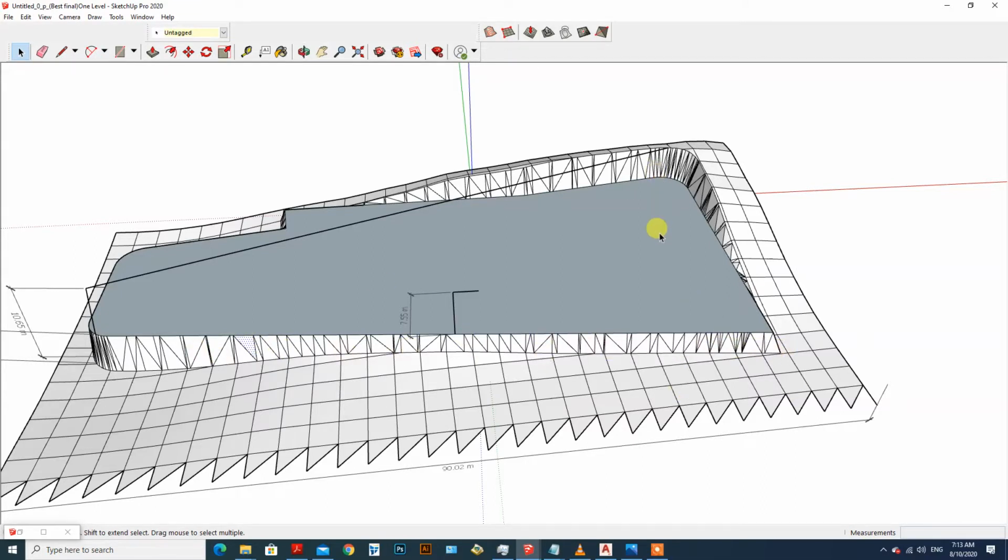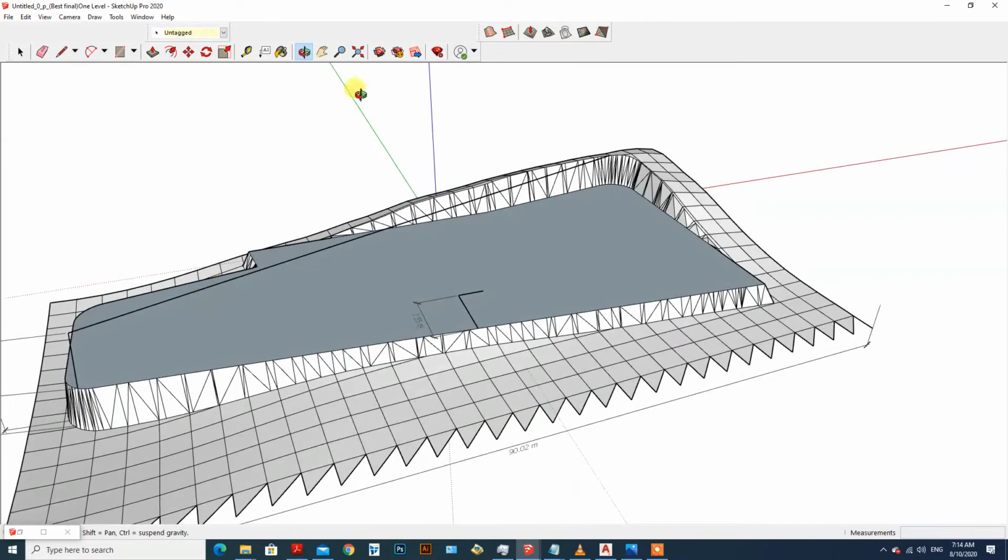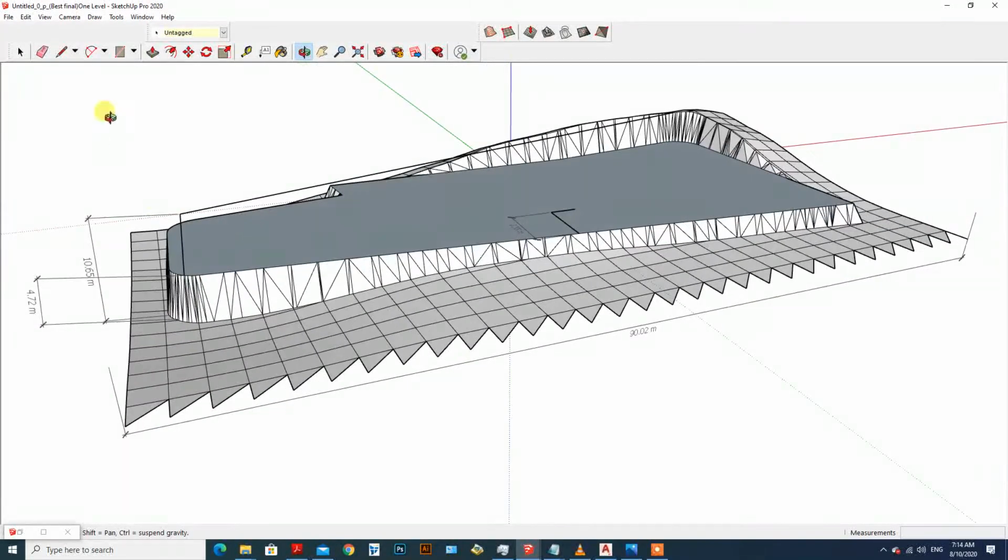It's going to be a slope. We do our cut, and this is going to be the fill face. This is the face of the fill, and this is the exposed bank. I was quite convinced that this could be the best idea, to cut the platform into a single level. This corner here is the main road, where it starts from West Road to enter the site. I was also able to figure out what the height would be. This corner will be the highest point, with a height of about 4.7 meters.